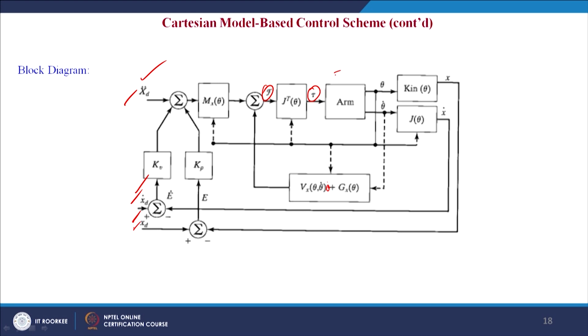In the same way, simulation is done with the dynamic model, and from the joint angles obtained from the simulation, we do the forward kinematics and differential kinematics to obtain the actual position and the actual velocity of the end effector tip.